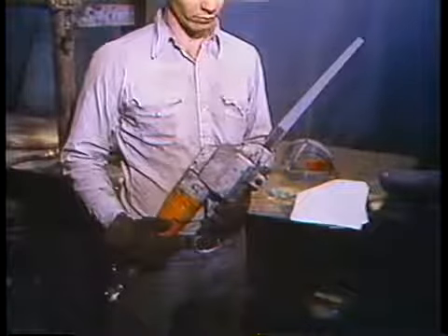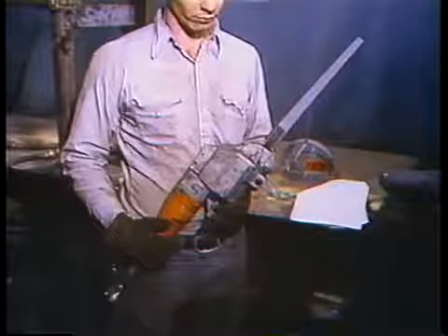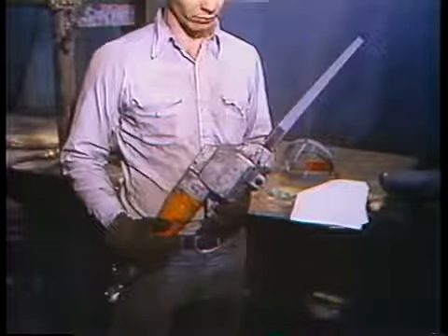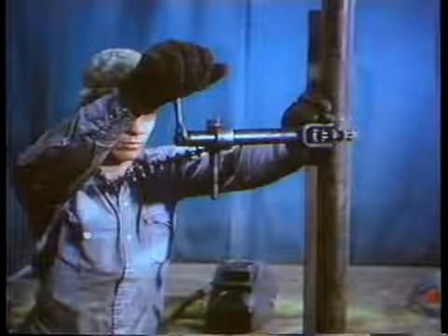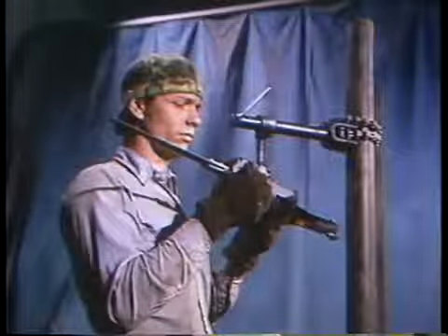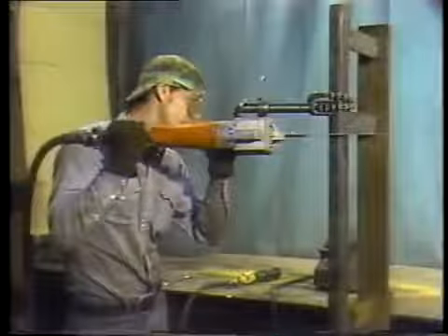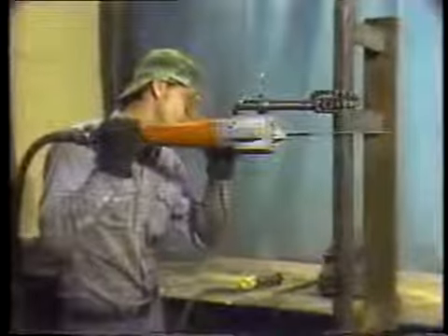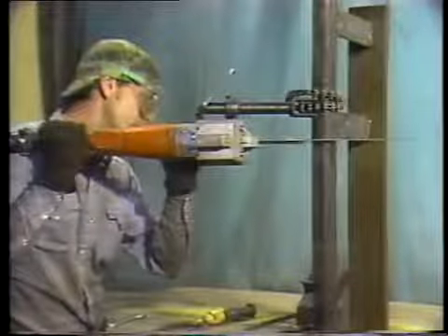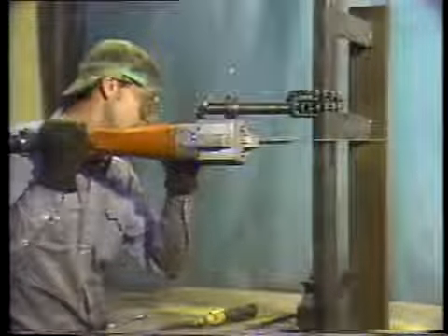Once preparations and precautions are finished, the procedure begins by cutting out the damaged section of tube. Here, we'll do the cutting with a saw. Now, this type of saw is attached to the tube that will be cut. This is done by attaching a clamp to the tube and then attaching the saw to the clamp. Cutting is done with a saw rather than a cutting torch to avoid getting slag inside the tube. Two cuts must be made to the damaged tube section, one above the failure and one below.